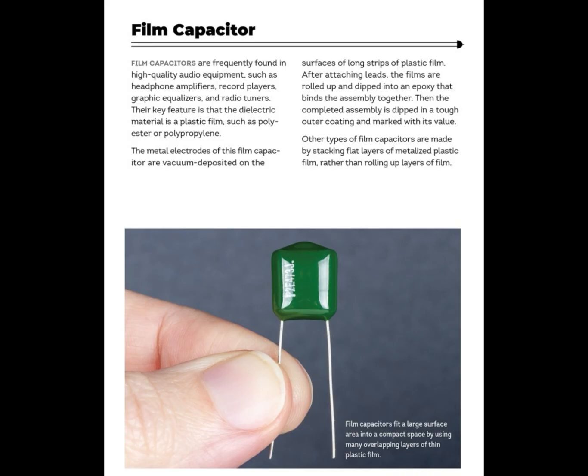It has four types. Number 1 is the commonly used for general purpose applications. Number 2, the polypropylene capacitor, known for better electrical properties and often used in audio applications. Number 3, polystyrene capacitors, often high precision and stability, used in timing and RF applications. Number 4 is the metallized film capacitor. Features a metal layer that serves as one of the electrodes, providing better self-healing properties.